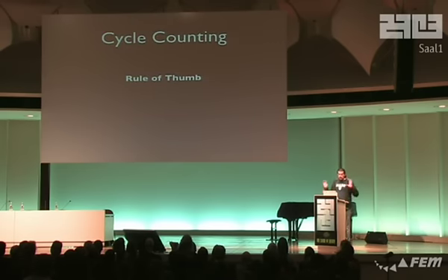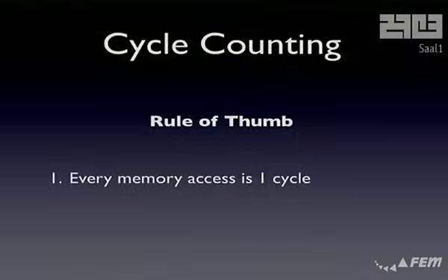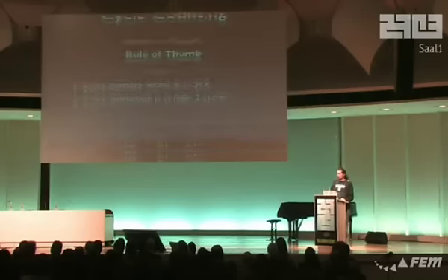What's interesting about an architecture like that, an 8-bit architecture, is that you know the length of your cycles, also about understanding what's actually going on inside, not just about optimization. So every memory access is a single cycle. The whole system is very memory bound, so mostly you only look at how many memory accesses you have for executing an instruction, and you know how many cycles it'll take. But there's the special case that every instruction takes at least 2 cycles.